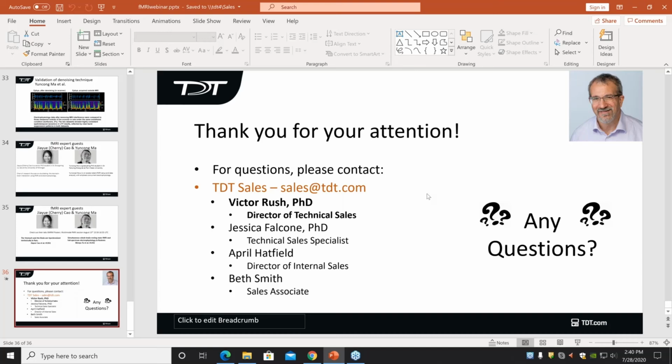All right, Victor, we do have one question from Thomas Marecci. He was wondering, do you filter out artifacts from gradient switching? So the answer is no. If you want to do that, you're going to need to do that offline. Any artifact that is picked up is either going to be rejected, we're just going to throw it out and throw out any signal around it, or you're going to have the complete recording session and you're going to be able to do that offline.